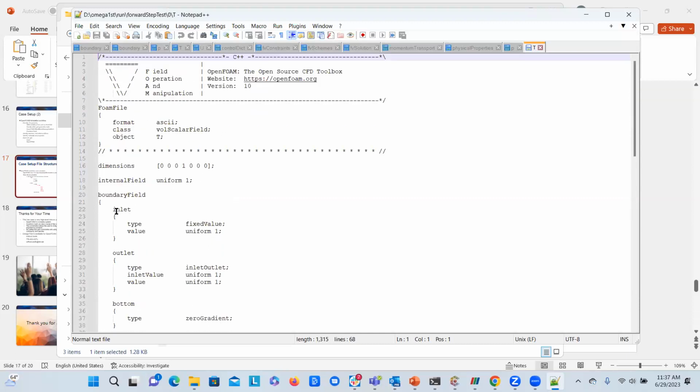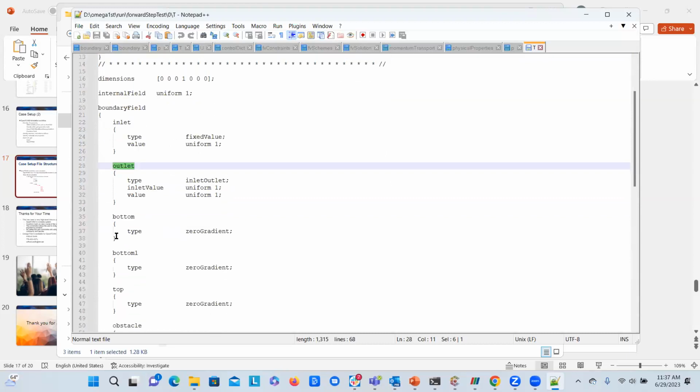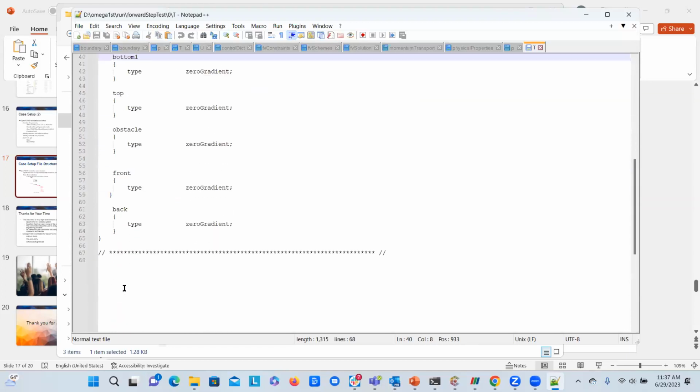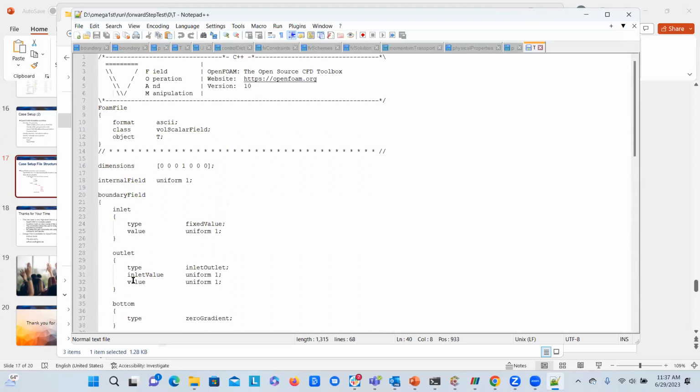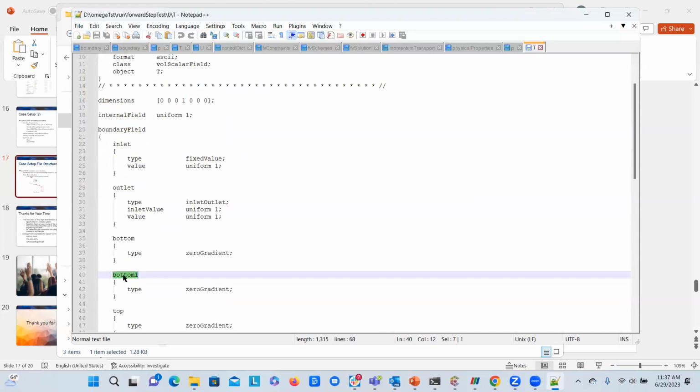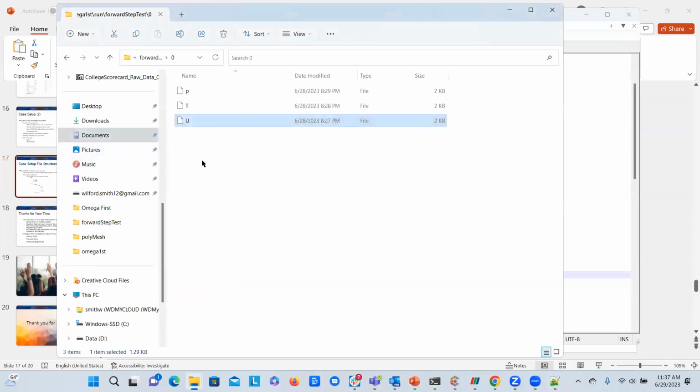Okay. The same thing, I defined an inlet condition, I defined an outlet condition within Cubit, and I defined all these various tops, bottoms on the Cubit. Within the Cubit itself, when it printed out the geometry and the mesh, it named the patches that were on these parts of the boundary. And now I have to go back in there and tell it what those patches actually have. Okay, and then finally, the velocity.